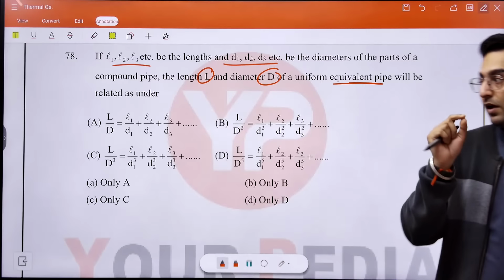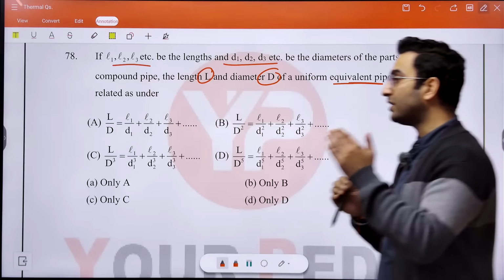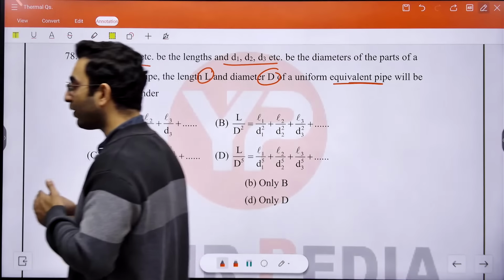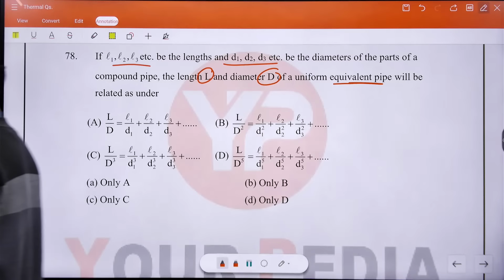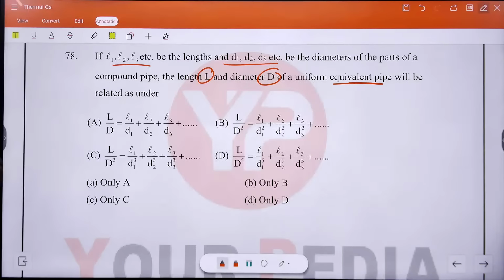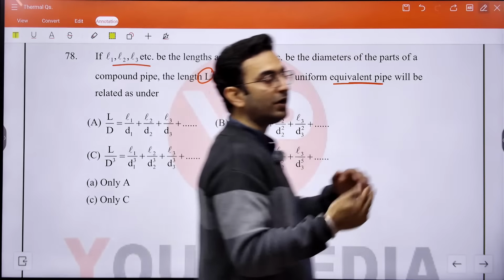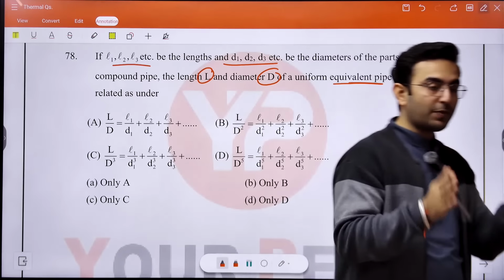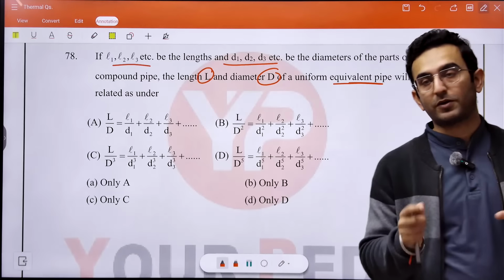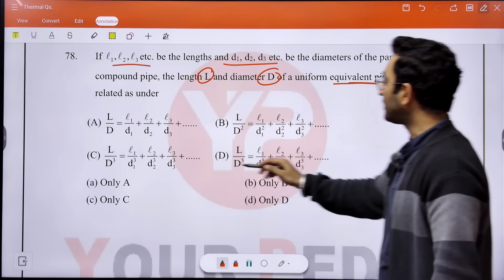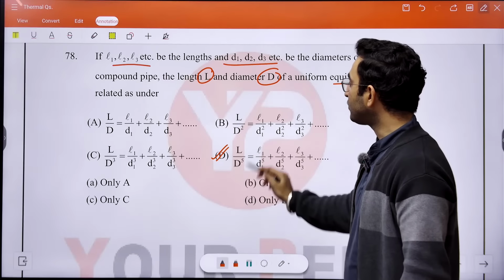First of all, multiple pipes can be connected in a series connection to increase the length of the pipe, or to transfer the liquid over a large distance. But the parallel connection is generally used for increasing the discharge through the pipe. Now, in order to convert multiple pipes into a single pipe of uniform cross section, we use an equivalent pipe.